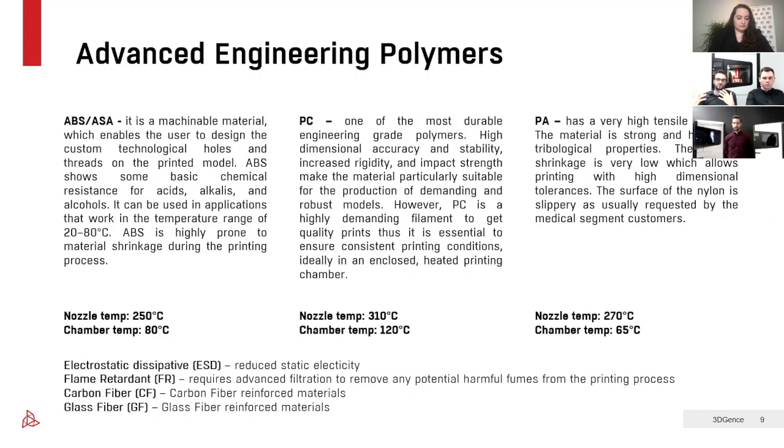And so the higher grade of ABS materials actually requires a heated chamber to prevent warping and deformation, and it requires a slightly elevated nozzle temperature, usually revolving around 250 degrees. This actually becomes really important. That's why we've made the choice to actually incorporate ABS in this section.